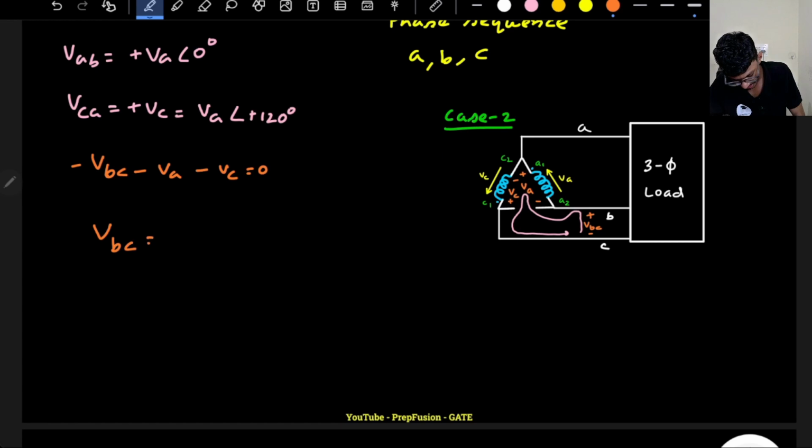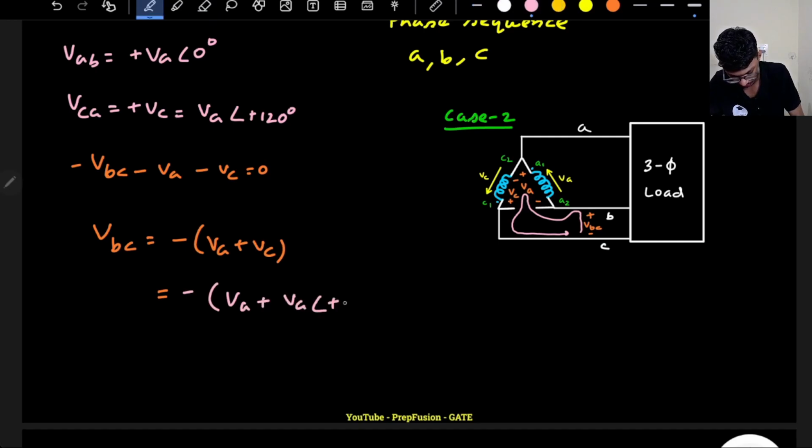So VBC is basically minus of VA plus VC. Okay, that is what my VBC is equal to, correct? Okay. So what is VC? VC is VA angle plus 120. So VBC is minus of VA plus VA angle plus 120.